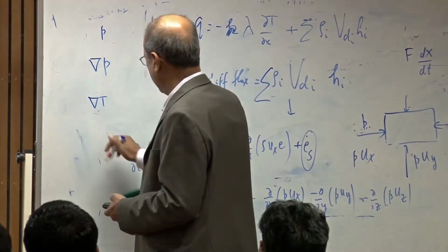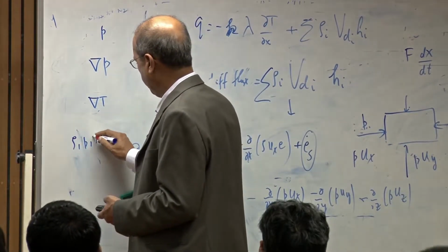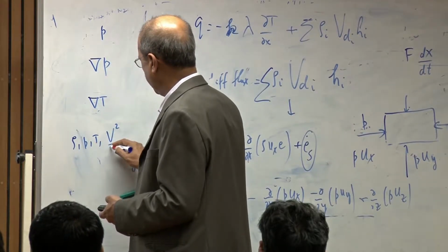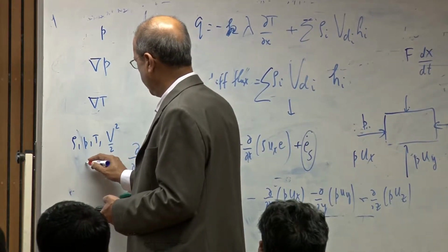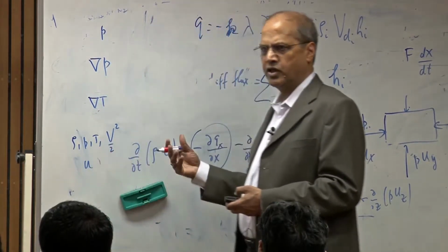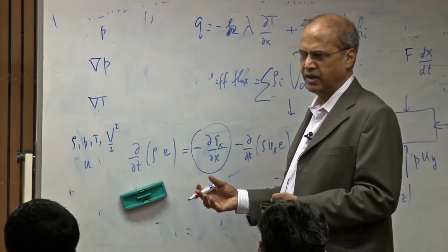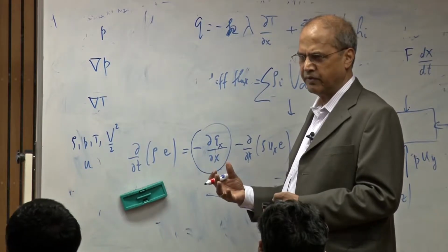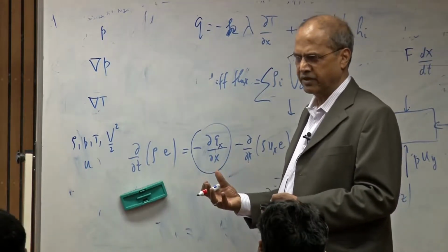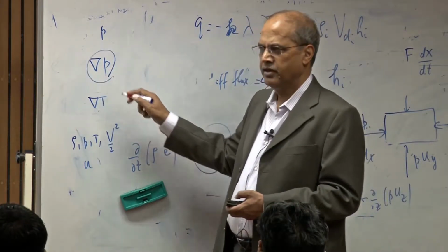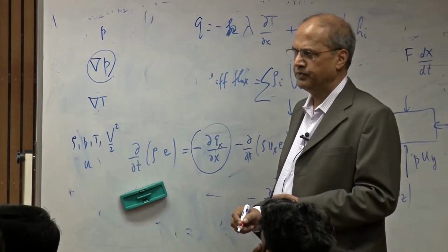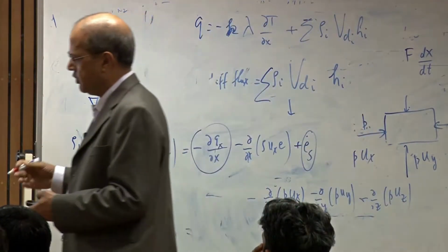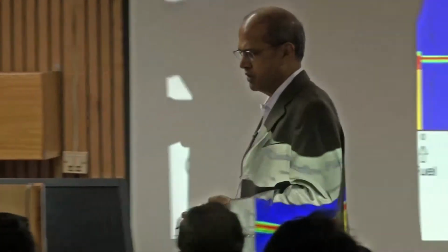The main scalar quantities are density, pressure, temperature, kinetic energy, and internal energy. Then we have vector quantities like velocity. Pressure is scalar, but when you write the force, it becomes a vector, because the pressure force is determined by the gradient of P. And for stresses you have tensor quantities, which have 9 components, everywhere in the flow.